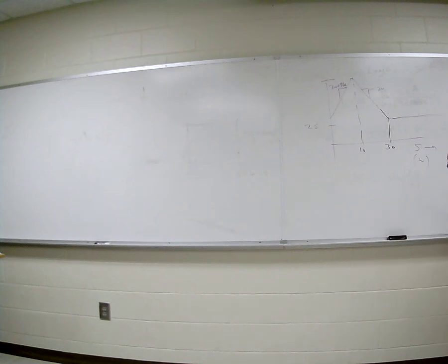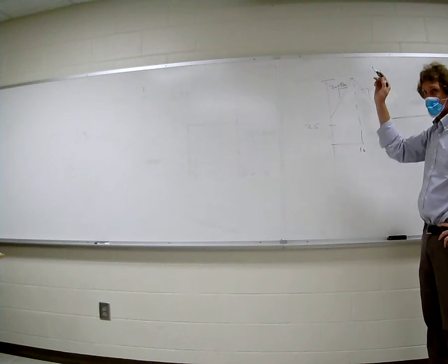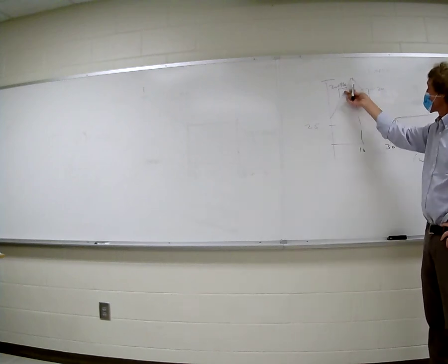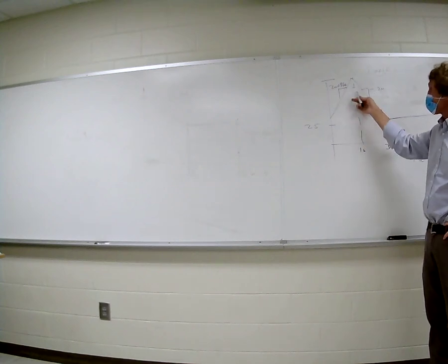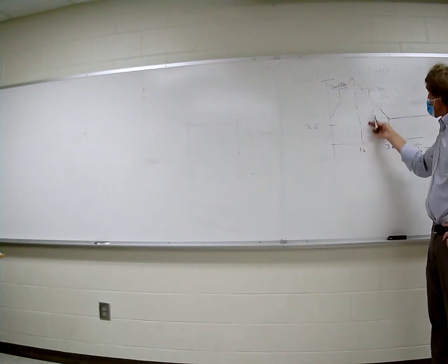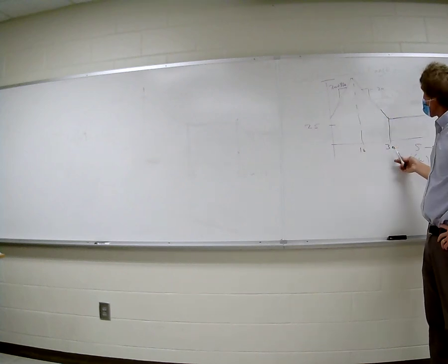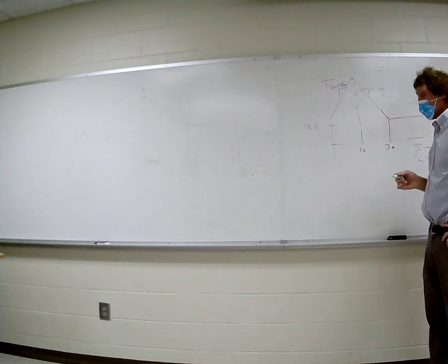All right. Let me show you how to do this, because this is a good one, right? We know basically what's going to happen. I have something increasing at 20 dB per decade from the get-go, so that's just S on top, right? When it hits this point, that pole, it starts decreasing at 20, so I have to subtract 40 dB from the rate of increase, correct? Then it flattens out here, which means there's another zero at 30 that is going to be on top. It would be an increase of 20, and it would start at 30, correct, class?